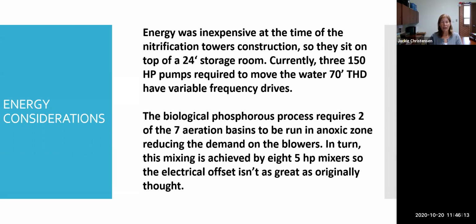They're a little different. They're magnet drives, which is a magnet actually controls the distance between the two magnetic plates. And as the plates distance increases, it slows the pumps down. So they are a little unique. Not a lot of people have those magnet drives. When we converted to the BioP from the chemical addition, it did take about 3 months to do that conversion, to grow up the PAOs sufficiently that we were within the compliance limit of 1.